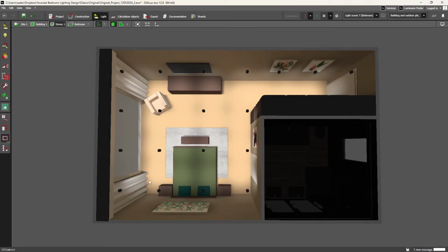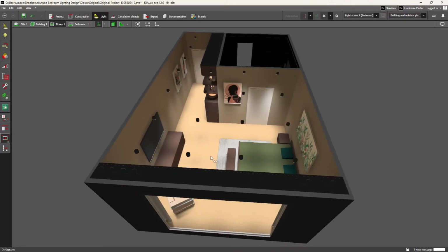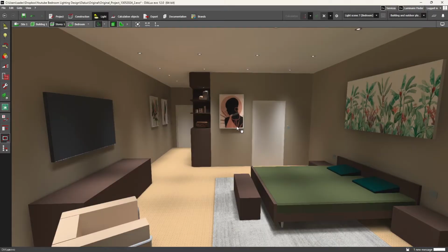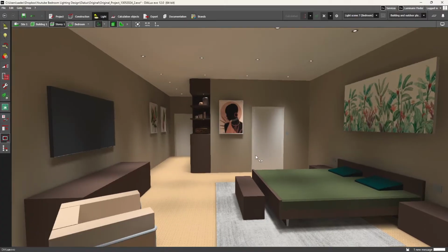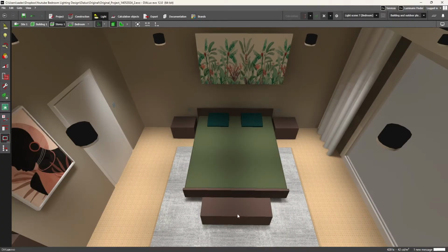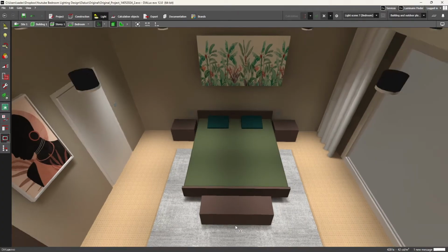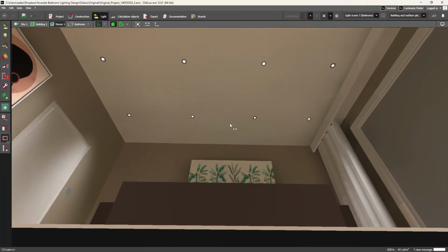The downlights here are part of what we would call ambient light, for the general illumination of a room. But here, the result is mainly flat, and the position of the downlights is not really matching the use and feel of this bedroom. For example, downlights right above the bed. I mean, really? Does anyone want the light glare directly on their face when waking up in the morning, like